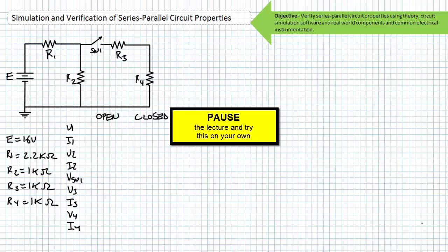As a refresher of the advice I issued in the voltage divider circuit lecture, I must emphatically remind you that the closure of switch 1 makes this an entirely different circuit and must be approached as such. Absolutely none of the values you obtain during the analysis of switch 1 while it is open can be used to solve for any other quantity while it is closed. These are 2 totally different circuits, necessitating 2 totally different analyses.